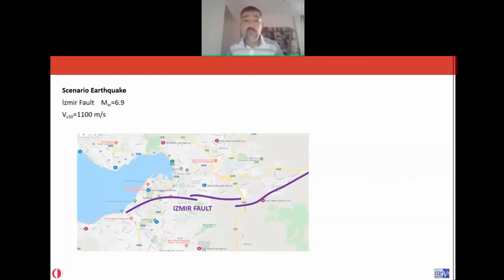We haven't stopped here because everybody is asking the same question. Remember, this is not an Izmir design basis event. We're talking about an event that happens 65 to 75 kilometers away from Izmir Bay. Rock motion PGA levels in Izmir are 0.05, 0.08 g. Sorry, did I say 0.9? I mean 0.05, 5% g, 8% g.